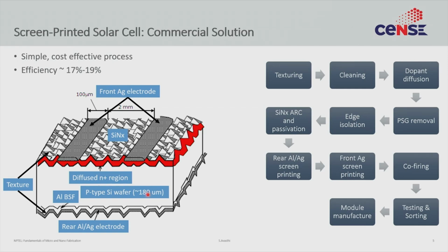But we see that there is only one N-type diffusion, right? There is no N plus. And that is to save on one diffusion. One less diffusion means cost saving. We realize that there is no P plus layer, but something called aluminum back surface field. Aluminum is a group 3 element, so at least theoretically it should be a p-type dopant in silicon. It's not commonly used because it's a little lossy, but again, silicon solar cells really wanted to optimize cost, and it turns out for various reasons the aluminum back surface field is very efficient. So we'll talk a little bit more about it later. For now, let's assume this aluminum back surface field is our P plus layer, so that is common.